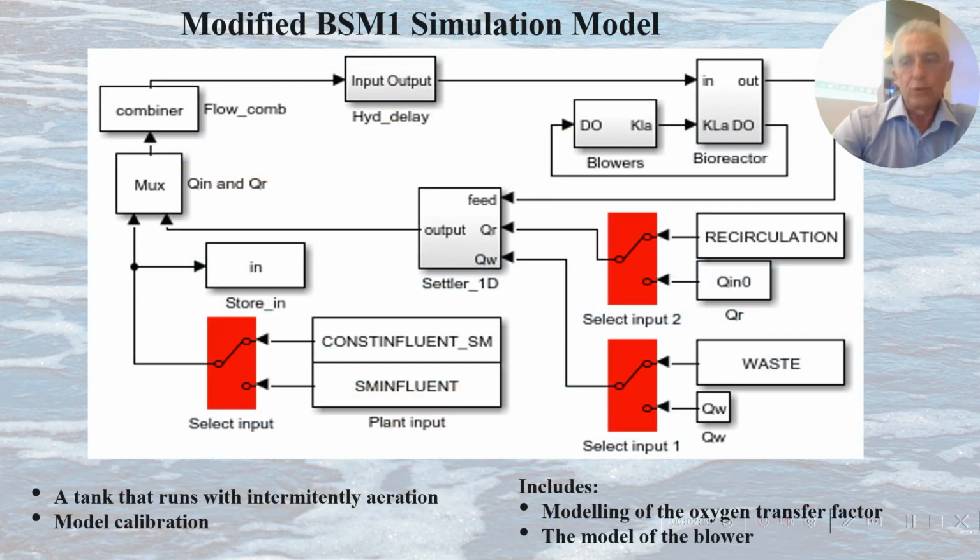To simulate and to test our method, we use the well-known simulation model BSM1, benchmark simulation model number 1, which is a platform well known to simulate the wastewater treatment plant. And this platform was adapted and we introduced new blocks to make the connection between blowers and the bioreactor.